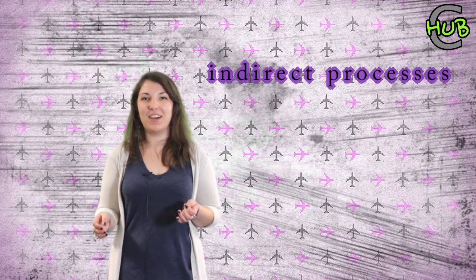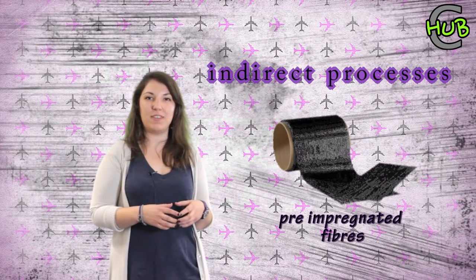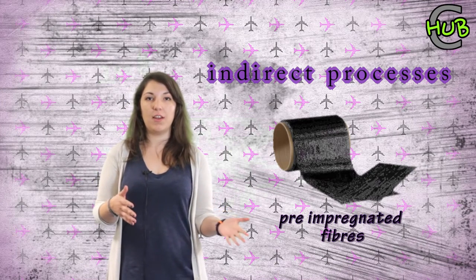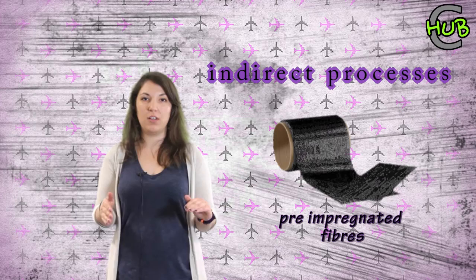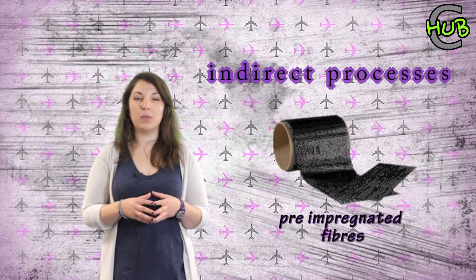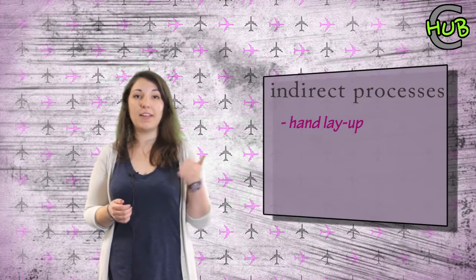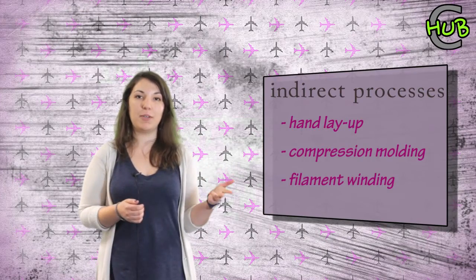Indirect processes are where pre-impregnated fibers are used. This means that the fibers are already mixed with resin and partially cured before molding. This type of material is commonly known as pre-preg. The most commonly used indirect processes are hand layup, compression molding, and filament winding.